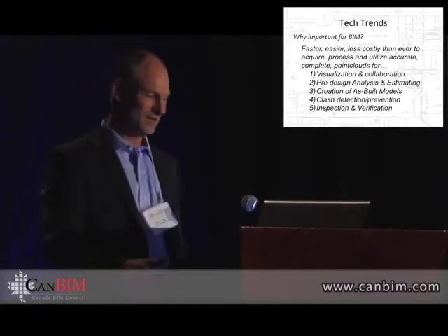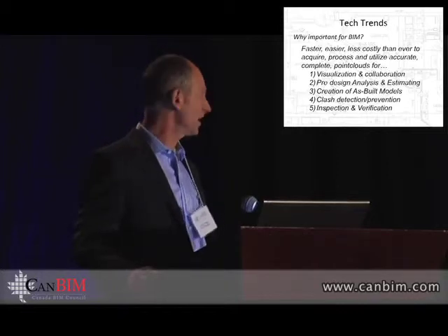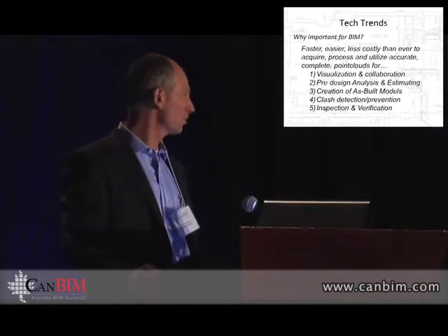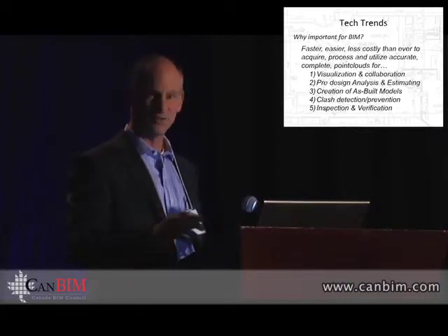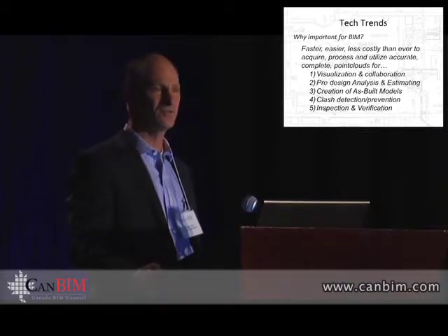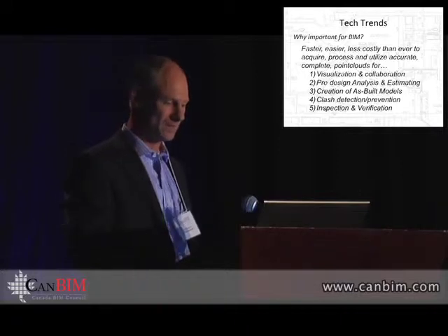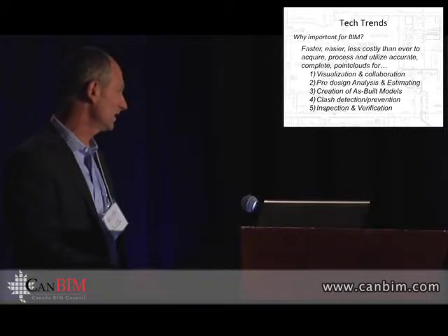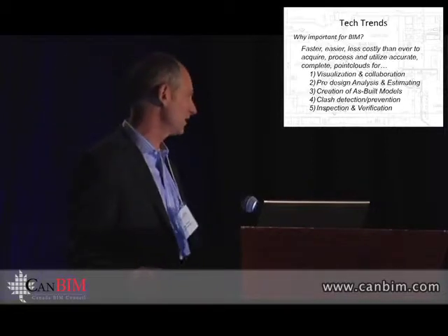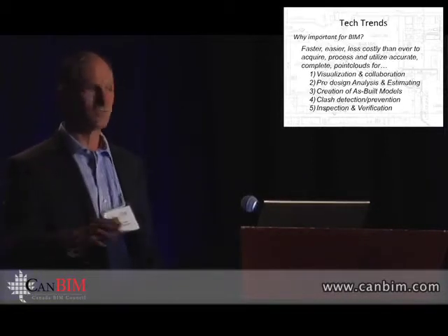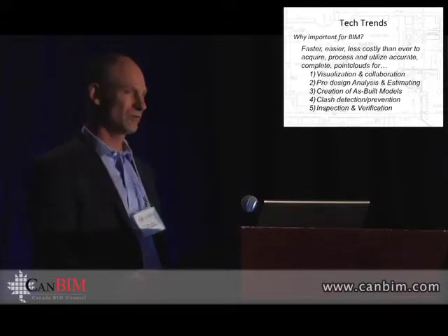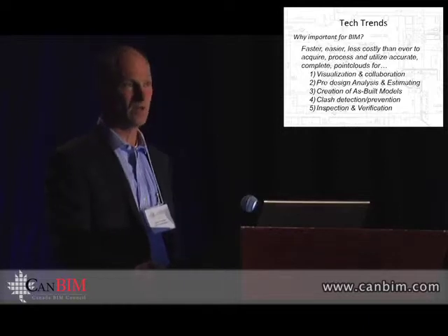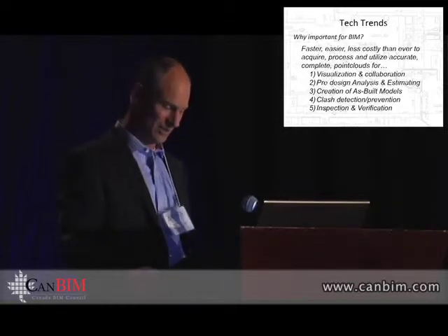So you've already got the data, and the data acquisition time is fairly fast. So they maybe do not do all the modeling and do all the work on the data set, but they can use it and get the dimensions and the things that they need to do an accurate and quick estimate. Obviously, the creation of as-built models, and we'll talk more about that. Clash detection is another big area. And then verification. We've got more and more customers actually doing scans after they've done some construction and verifying back to the CAD model that, yes, it is conforming to what the client wants.